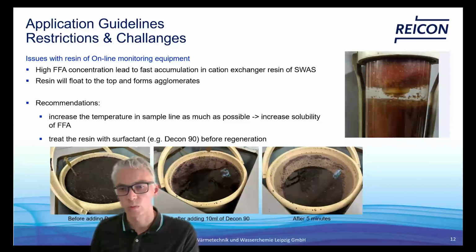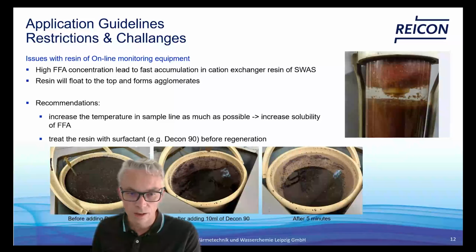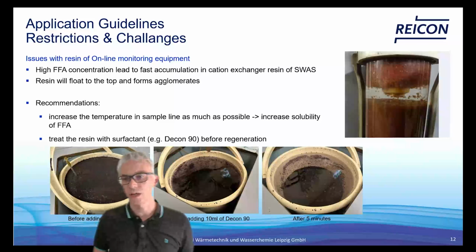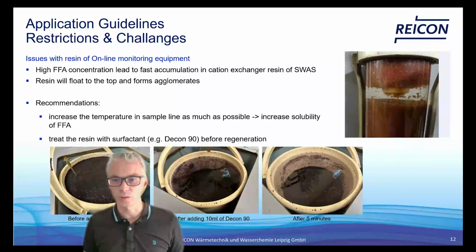Or what we see is that you can treat the resin with a detergent or surfactant. Here, for instance, we use DECON 90, and you can see that before adding the surfactant, a lot of resin is swimming on the surface of this bucket, and right after adding a few milliliters of that DECON, it sinks, and after 5 minutes, most of the resin has gone down, and after that you can do a standard regeneration process, and the resin can be used again.